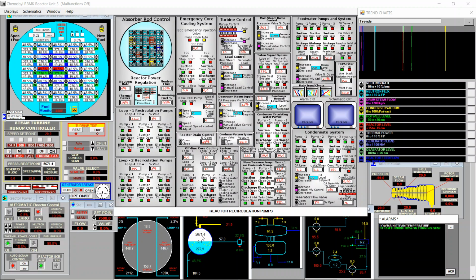Okay, and we're approaching the 7500 pressure we need, so I will start reducing power set point to 15%. And I will start opening the valve in the turbine. If we do things by the book, we need to open this when we reach 7500 of pressure in the drum. I start before just to save time. I will open to 10% and now decrease power set point to 10.